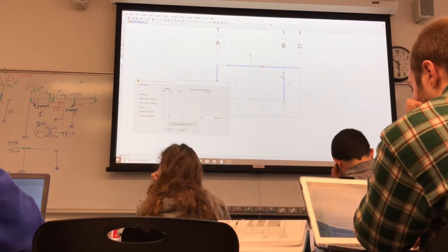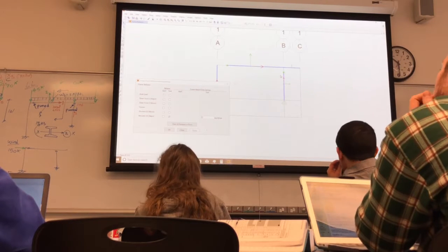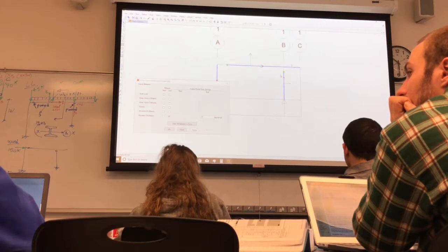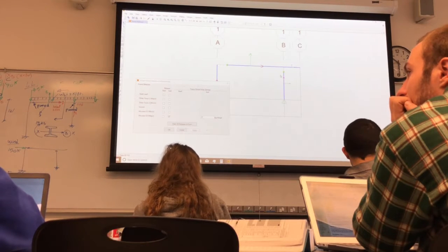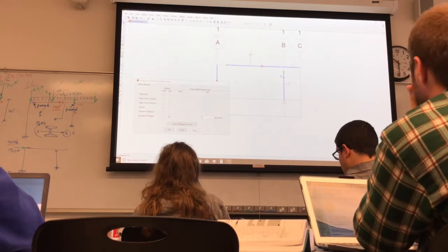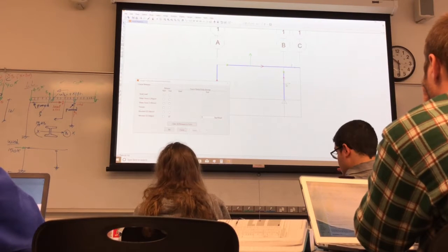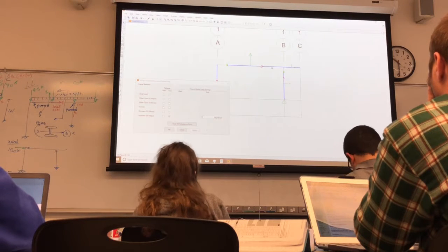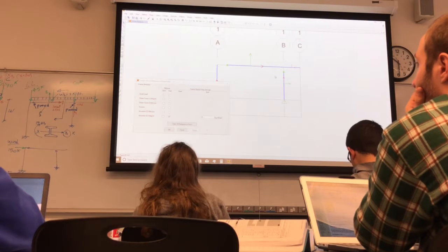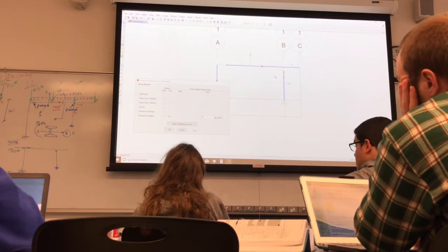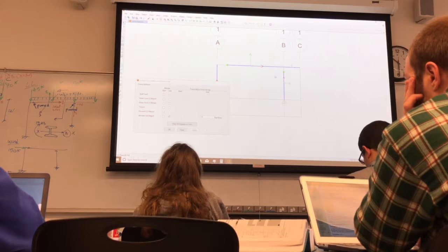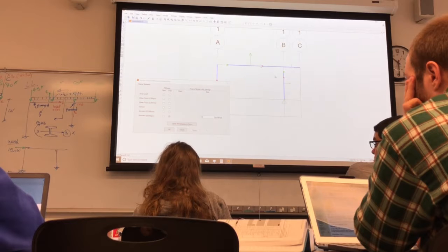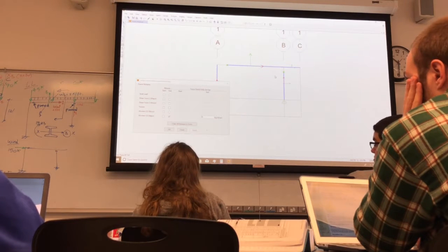Question: so we release the bottom column instead of doing the ends of the top? Because the top beam is one continuous beam, but we just had to draw it in SAP as two different ones? Yeah, that's a continuous beam, all the way across. It's not released. Because remember last class I showed you the connection? The beam is continuous like that. You have a column here, and then this column, the beam is continuous, and the pin is in the column, right?